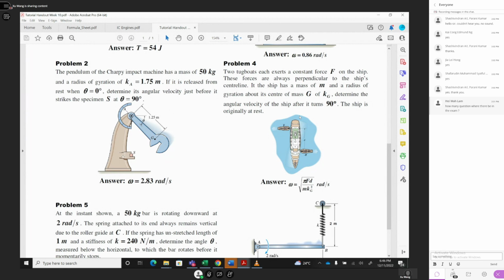You know, tangential velocity divided by radius equals theta dot. So half of I theta dot squared is this rotational kinetic energy, plus the center of gravity velocity term, half of m v_G squared. That gives the conservation equal to mgh, where h is the initial gravitational energy height. That's how to solve this problem. So we come to the solution.